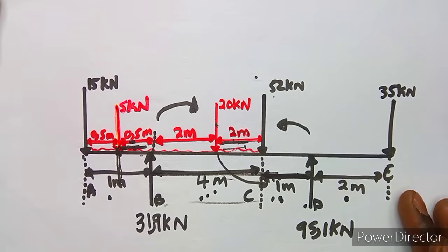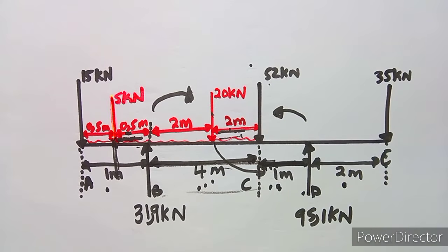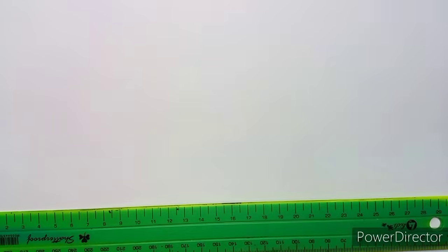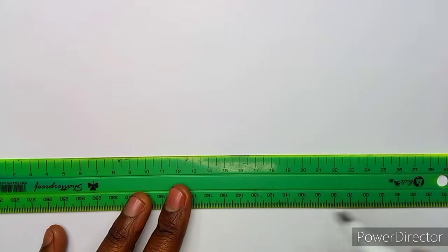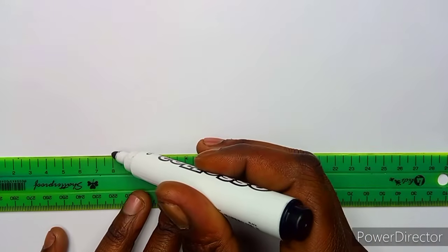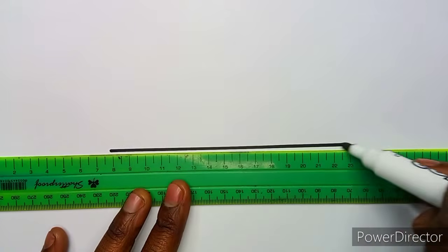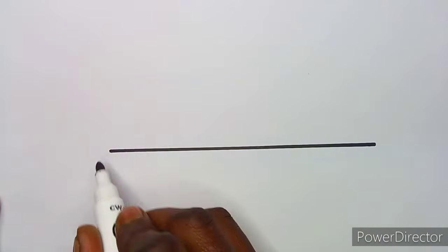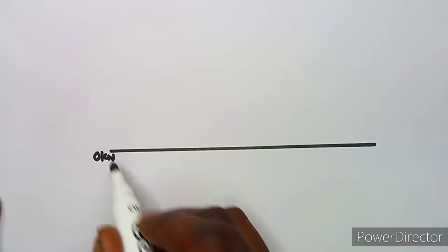So in order for us to have the shear force diagram, we have to consider the forces, how they are being taken, and how we are moving. Okay, so this is it, guys. Let me just save my line here where I'm going to have it. So I'm just going to indicate the important points, how they are supposed to be taken. Like so, as you know, guys, definitely you have to start at 0 kilonewton there at ground.